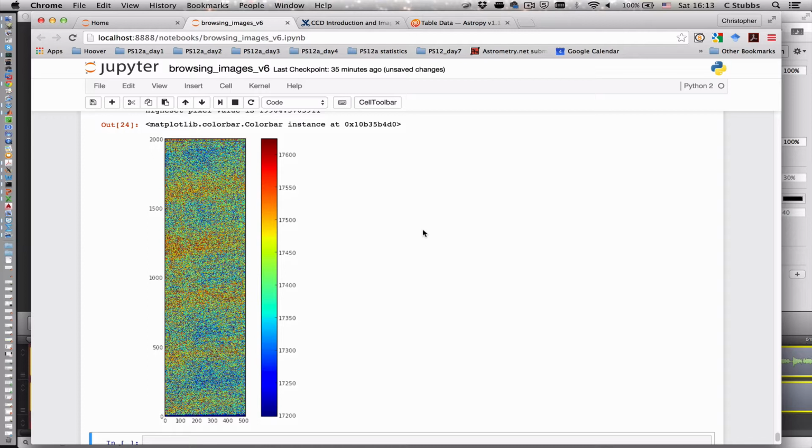that we saw when we made column plots of the array. So the fact that this bottom edge has diminished flux values is the edge roll-off down at the serial register. This dark line across the top of the image is that one dark row that we attribute to some mask defect up at the top. And you can see there's this sort of high flux structure up at the top that's the resonance off of that midline bleed stop.